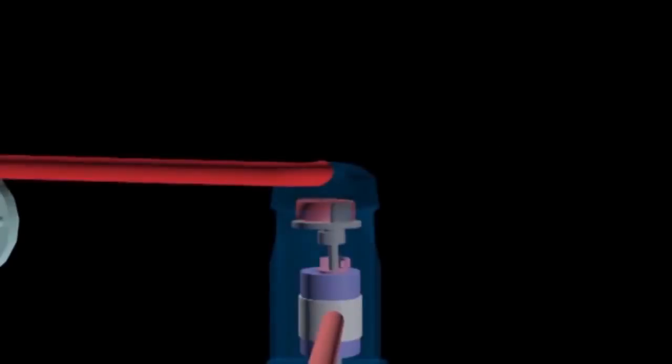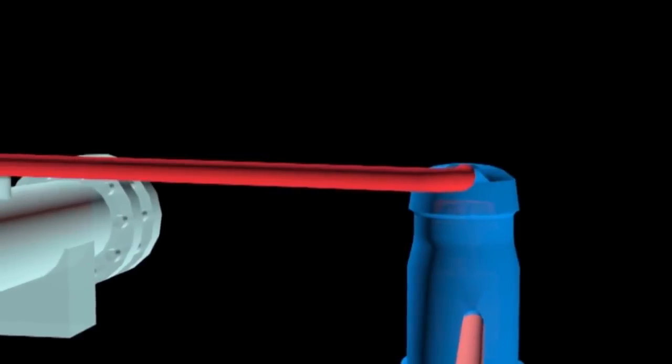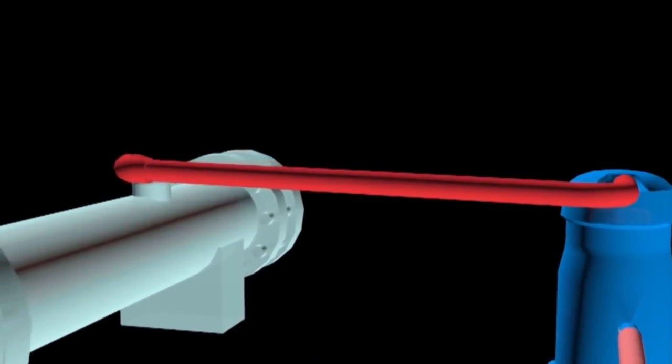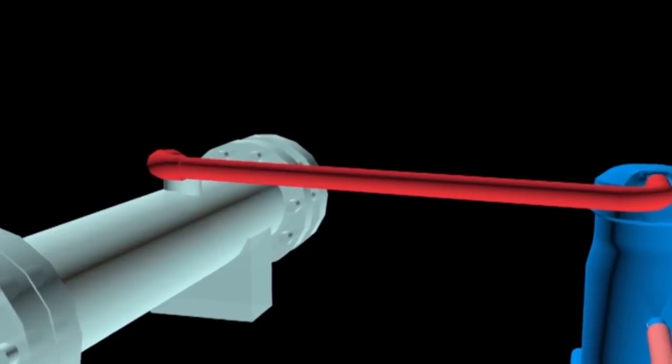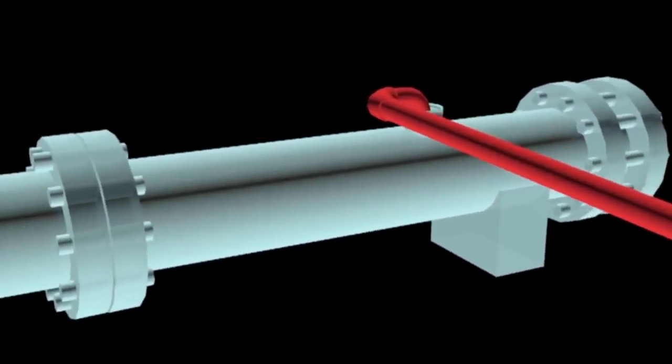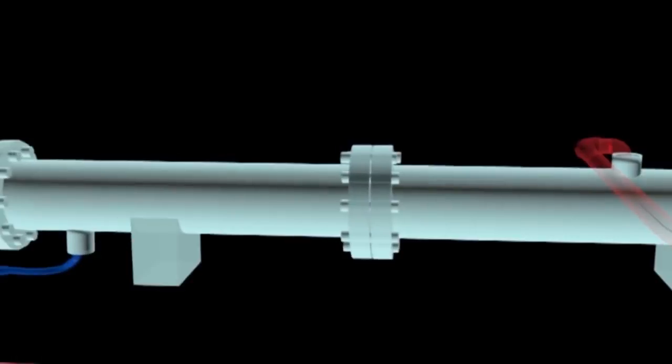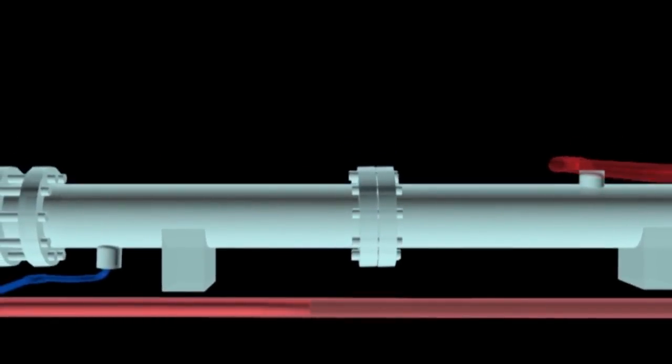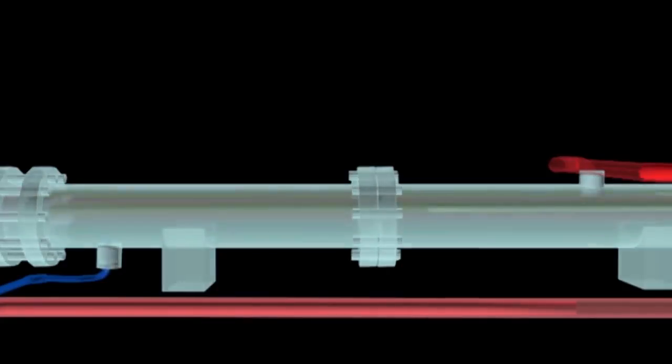Condenser. The refrigerant in high-pressure gas enters the condenser at a temperature higher than the temperature of condenser water. In the condenser, the heat will be eliminated to the condenser water from the cooling tower through the process of convection and conduction. After the heat is removed, the refrigerant in high-pressure gas is condensed into a high-pressure liquid when leaving the condenser. The condenser most commonly used is the shell and tube type. Water flows through the tube while refrigerant liquid is flooded in the shell.